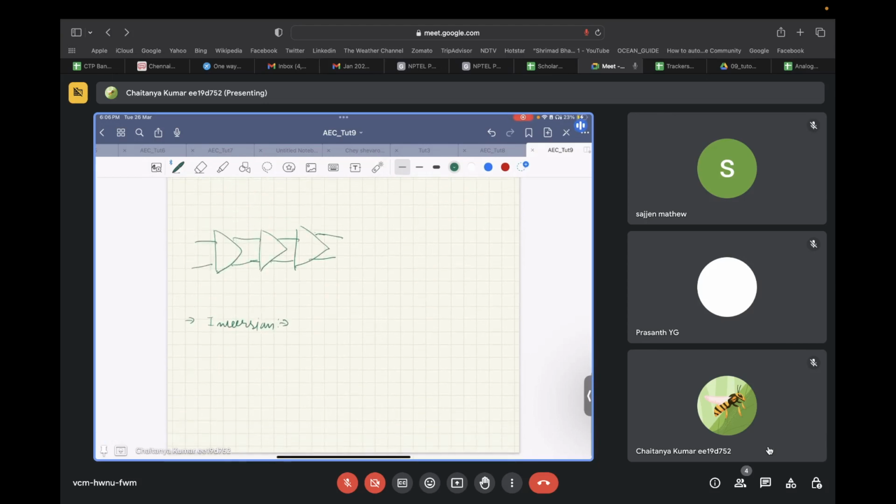To invert the signal in a single-ended chain, you will basically need an analog buffer with a gain of -1. How will we build that? Any idea how we will build an analog buffer with a gain of -1? One of the most common circuits to do this is an inverting amplifier.